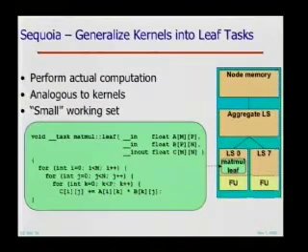So this is sort of a bottom-up way to view how a Sequoia program looks. And I'm showing it in relation to an IBM Cell, which is what we're using currently as our target for the Sequoia programming system. So the Cell has 8 synergistic processing units. I like to think of them as stream processing units, because otherwise it sounds like a Toyota hybrid vehicle or something. Each of them has a local store, which I always forget whether it's 128K or 256K bytes, but it's 256. It's less than you would like because your code has to fit in there as well.